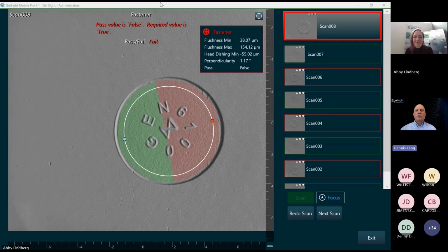So we were bringing those into our software platform and allowing those inspections to be enabled by our very unique hardware that was also being developed in parallel, being robustified, becoming smaller, easier to use. So now we're in the field looking at early stage corrosion when fasteners are removed around joints. Again, we can actually look at the sealants themselves, even if they're clear. That's one of the huge benefits of the gel and GelSight, in addition to not needing those supports and some of those other things. We can confirm the fastener seating in seconds, as you saw here.